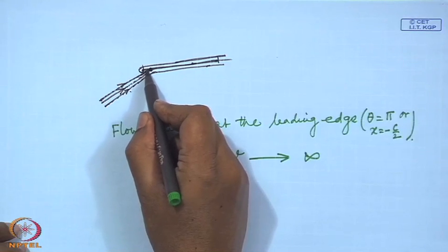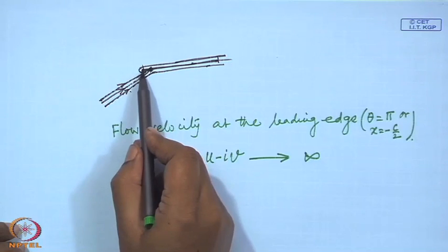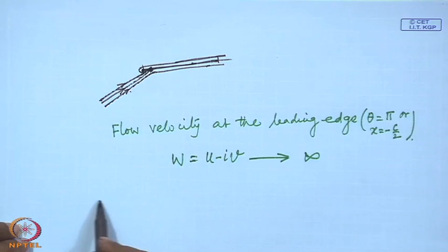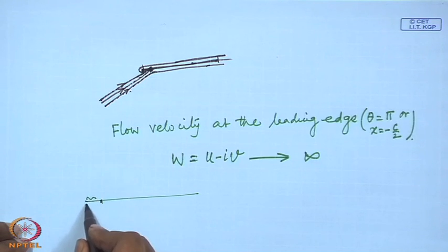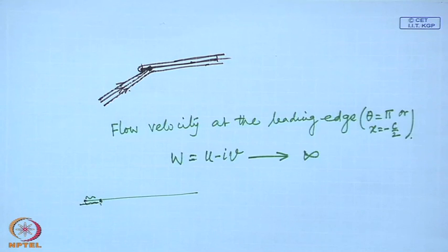at this point, which is the stagnation point, from here as we move to this side, which is part of the upper surface, the front part of this flat plate, which is ahead of the stagnation point, and this part on the lower surface, flow velocity is increasing from 0 to something. Here it is becoming something undefined. You are calling it infinite in the sense that this is going on increasing, the flow velocity here is 0 and then gradually increasing, and here it is undefined. It is okay, you are saying very large, because it was very large ahead of it.